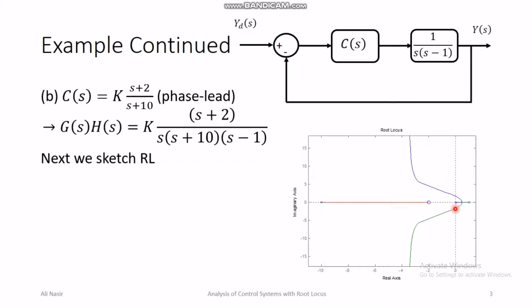You can find the point of j omega axis crossing using the 8th rule of root locus. And then if you keep on increasing the gain beyond that point, both of these poles enter the left half plane and the system becomes asymptotically stable. And beyond that point, for all the values of gain larger than the value for which j omega crossing occurs, the root locus has asymptotic stability maintained.